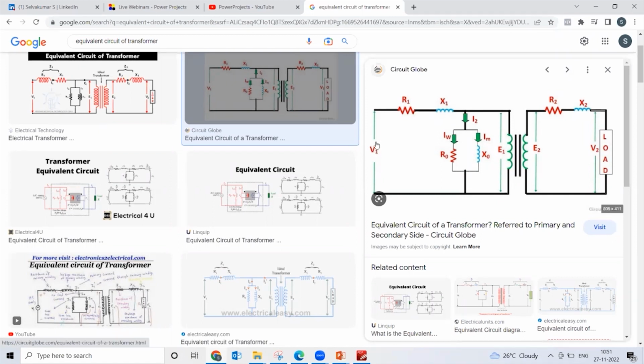And what is the voltage or current to be measured when that is reflected on the secondary of the instrument transformer, CT or VT, whatever it is? The behavior of this device is not the same for 50 hertz, it is not the same for 250 hertz, not the same for 350 hertz, not the same for 500 hertz. And we are measuring here something that probably has a different effect from what is available on the real high voltage, high current system. We are measuring in low voltage, low current systems, but this behavior itself is different, and by just multiplying the ratio we are assuming the same harmonics are there on the HV side, which is not practically right.